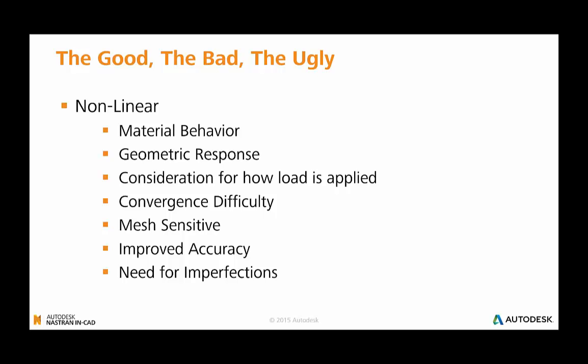And again, this is mesh sensitive. You can get improved accuracy over linear analysis types, but we also need some type of imperfection in the analysis, and we'll highlight this today in the example that we work through.